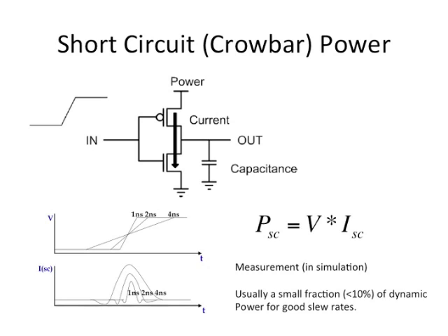When my input levels are static at either logic high or logic low, only one of the pull down or pull up stack is on, the other is supposed to be off. But during the transition, both will be on for a short duration of time. That duration is given by how fast or how slow the input transition happens. So during that transition, if I am going from 0 to 1 at the input, the output is discharging, right?